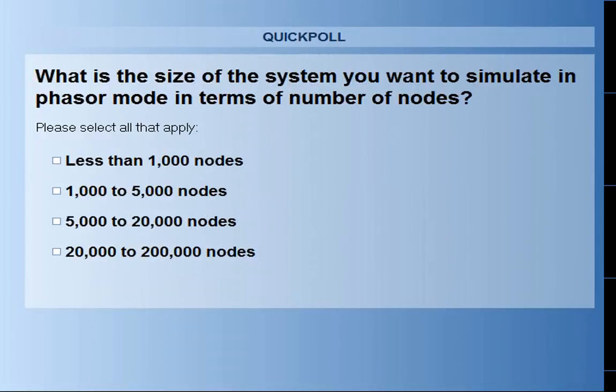Here we can have a PSSE file or an Excel file, but here I'm using the Excel file. You put in a time step, which in this case is 10 milliseconds. I will briefly go through the Excel file to give you an idea of how it looks. As you can see, it's a very simple template with multiple tabs, and you can describe your network here. You have pages for bus, for example, machine, the exciter controller, system stabilizer, and several other things.